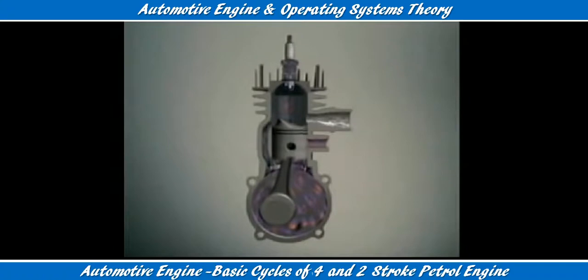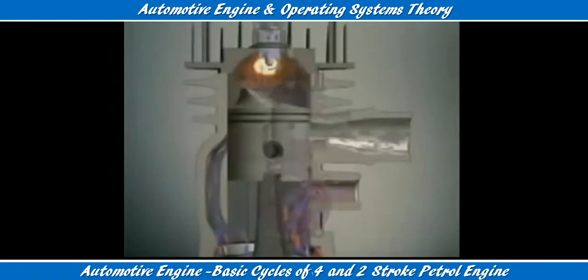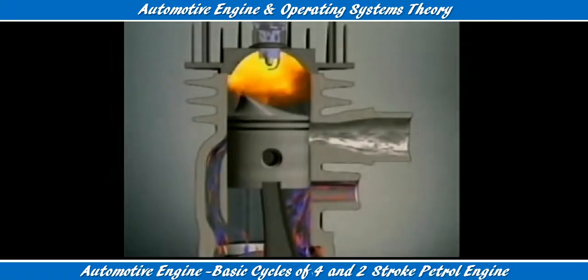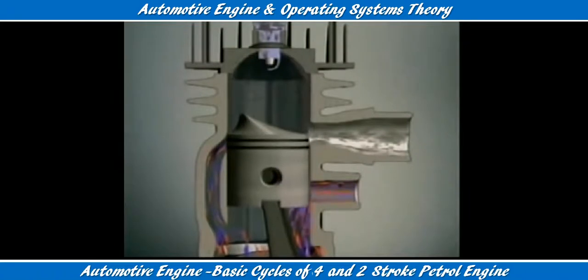The piston moves up the cylinder. The top of the piston covers the exhaust port, the bottom uncovers the inlet port. Air-fuel mixture enters and circulates in the sealed crankcase below the piston. The piston rises and compresses the mixture above it. A spark plug ignites it and it burns. Pressure from the expanding gases pushes the piston down in a power stroke.